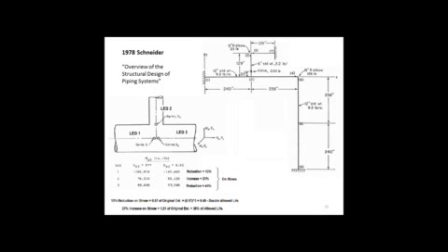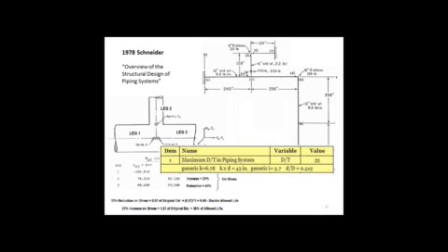Okay, so here's a simple model. This slide shows drawings from 1978 literature from Schneider that illustrates how intersection flexibilities can affect piping systems. So this simple system shows a 21% increase and a 41% decrease in certain of the piping legs. If we take a look at the criteria that we talked about for this system, the D over T ratio is 33. It's below 50. So we say, well, we got a 40% change here, which would be pretty significant for a pump analysis. So why did we get this change?